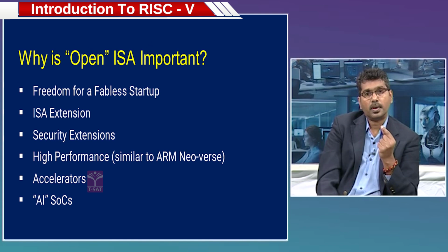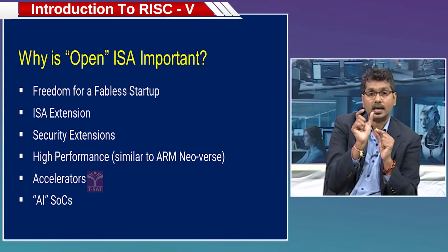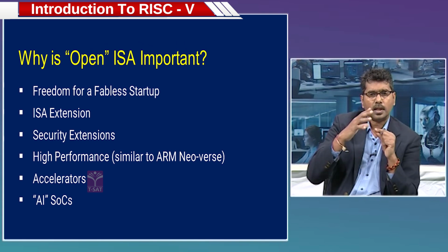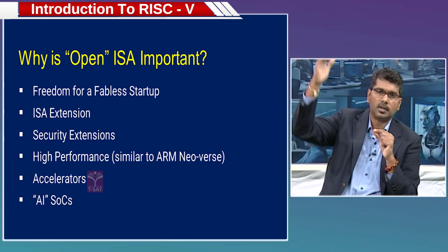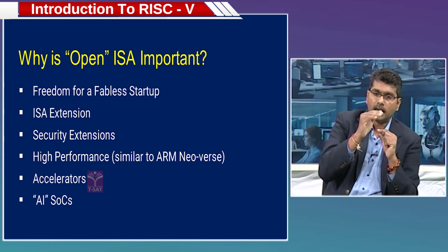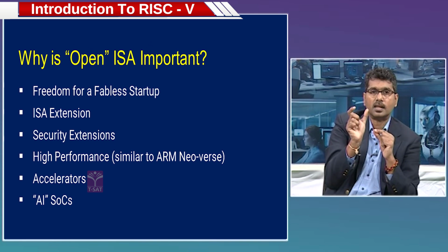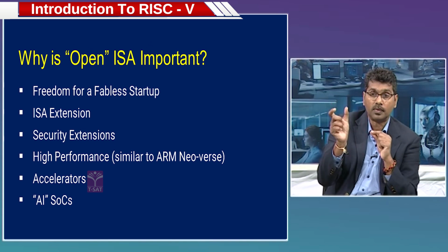This is extremely important. With RISC-V, you can add security instructions at the instruction level. Normally, for security, people add some different modules and do something in software. There's a whole host of work. But with RISC-V, you can extend it at the instruction level itself and do some security-level work. Because it's open, you can do that. This is very important for a lot of government projects.